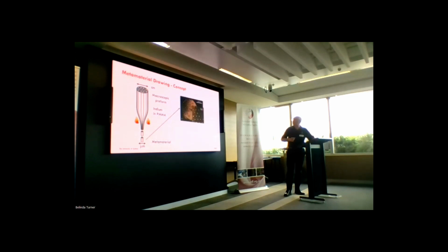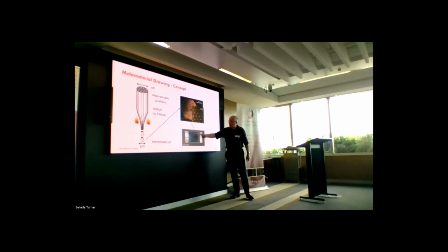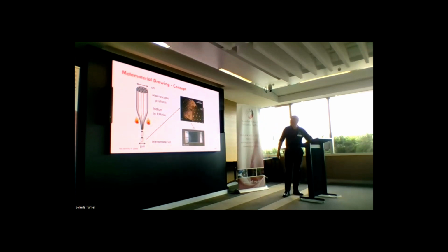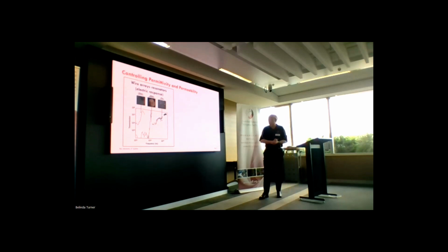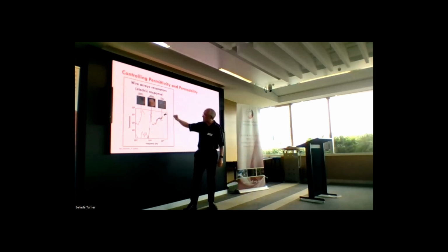So this shows a cross section there. The little bright spots are the indium reflecting in the microscope, showing we can get a pretty good ordered array of those. So we took these short segments and lined a whole load of them up. So we've got a planar structure of a metamaterial, and we exposed that to a terahertz time domain spectroscopy system, and we drew them to several different sizes.